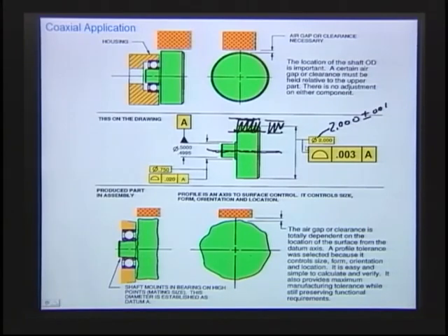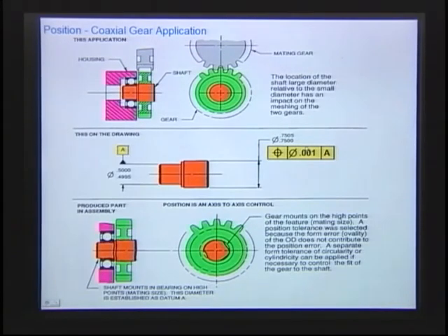All right, let's take a look at the next one here. Now, remember a little while ago we were looking at this one. This was our gear again. This here is my datum. Remember, a little while ago we had a position. Well, in position, could we have put a profile on here instead? Could we use profile over here, and we just say profile within 1? Well, no, I don't think you could.